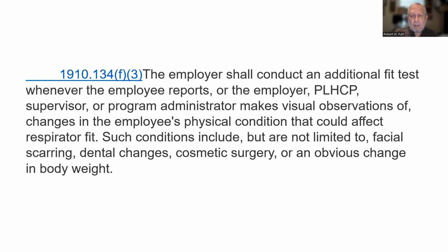The employer shall conduct an additional fit test whenever the employee reports or the employer, PLHCP, supervisor, or program administrator makes visual observations of changes in the employee's physical condition that could affect respirator fit. Such conditions include, but are not limited to, facial scarring, dental changes, cosmetic surgery, or an obvious change in body weight.